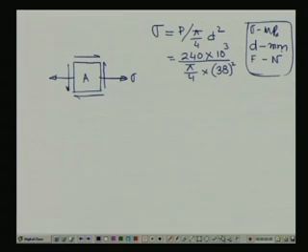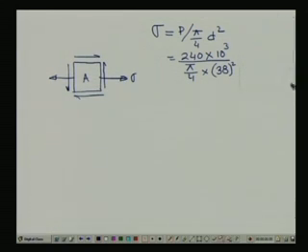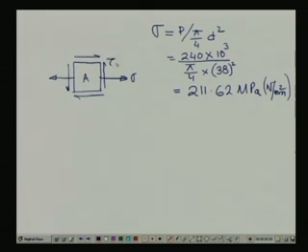At this moment we just come down and concentrate on the problem. Since the force is given in kilonewton, we have transferred it to Newton, pi by 4, diameter in millimeter, it stays the same. So, this gives you a value of 211.62 megapascals. What is megapascals? Basically, it is Newton per millimeter square. Now, once we get this, we do not know the value of tau.